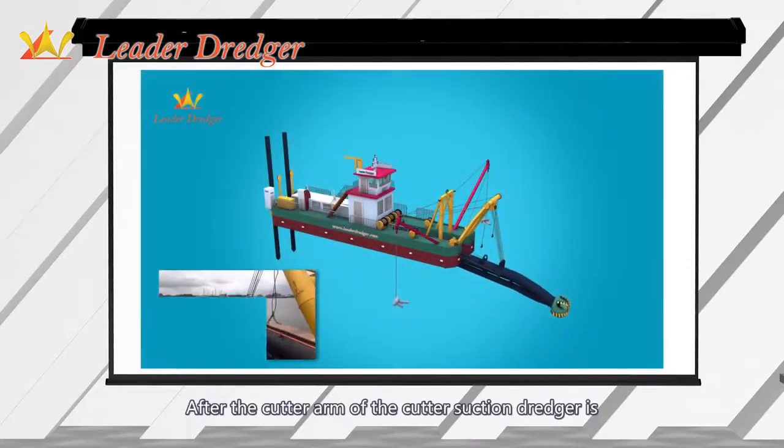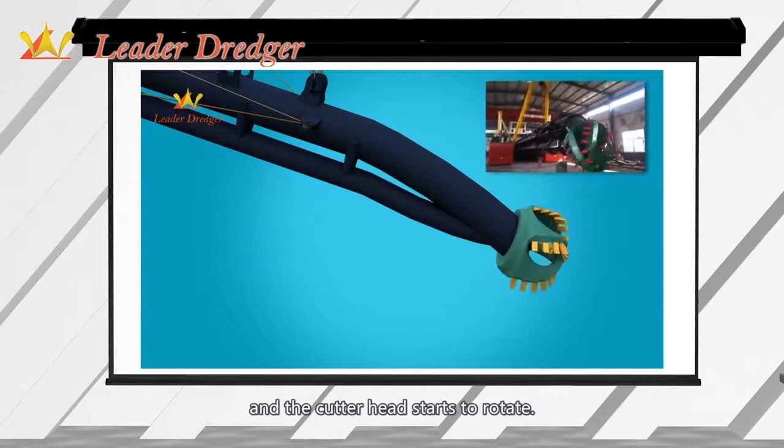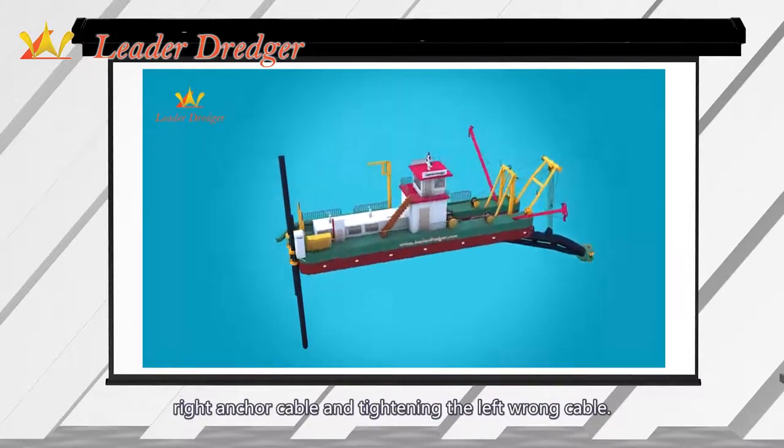After the cutter arm of the cutter suction dredger is put into the water, the dredge pump starts to work and the cutter head starts to rotate. The initial movement of the dredger around the positioning pile is accomplished by relaxing the right anchor cable and tightening the left anchor cable.